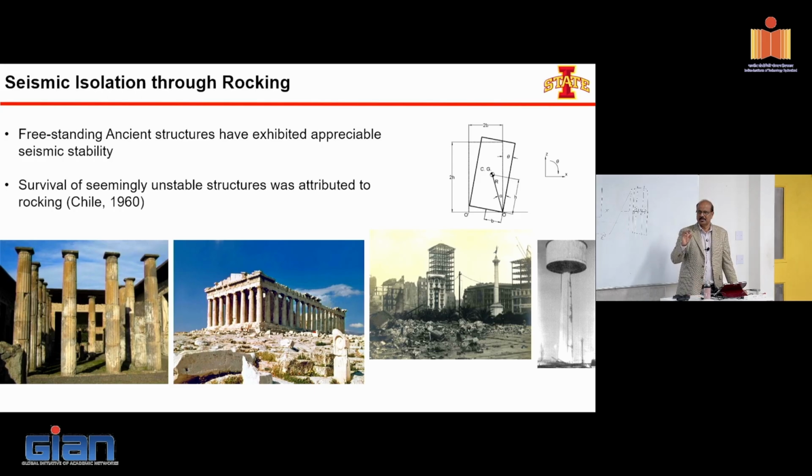We're looking at 25 millimeter, 30 millimeter thick rubber. The only challenge is replacing those rubbers after an event if it gets bad. So we would put the rubber only at the end regions where we can hopefully remove and replace it. So for single rocking wall, that's another thing that we looked at.